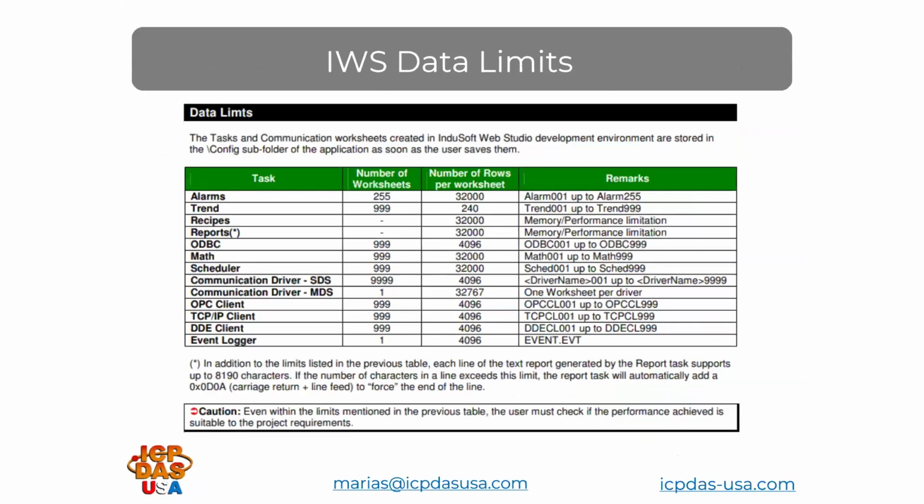InduSoft and AVEVA are flexible and very expandable. They support up to 999 trends, 32,000 alarm recipes, reports, math and scheduling operations, and 4,096 OPC, TCP/IP, and DDE clients and data loggers.